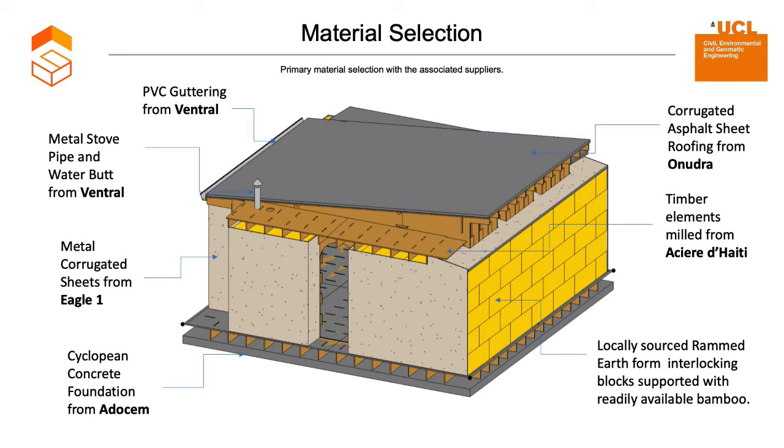Moreover, the foundations were debated as to whether it should be a raft or utilise gabion baskets. However, after research, it was found that gabion baskets are subjected to wear and tear and require frequent inspection, which would not be suitable for this project.